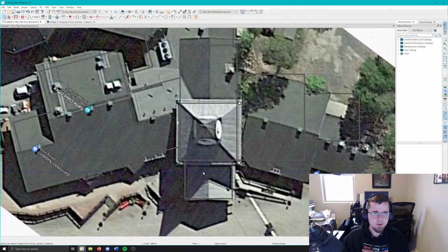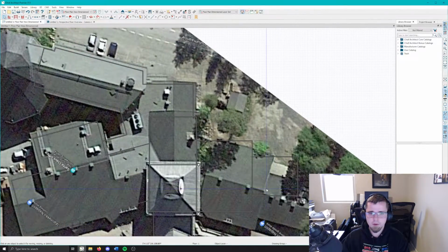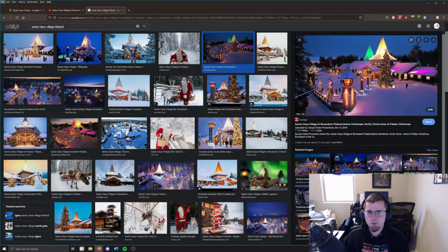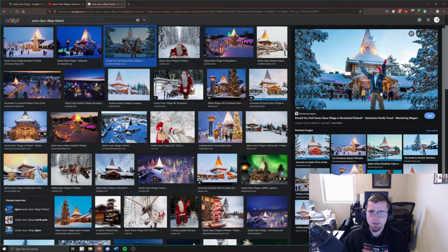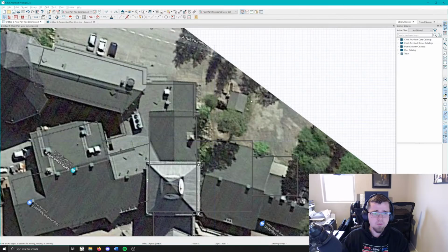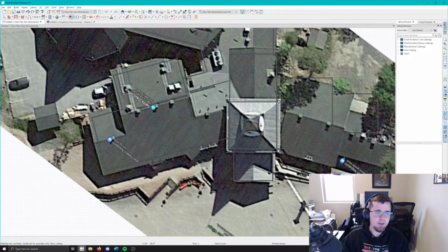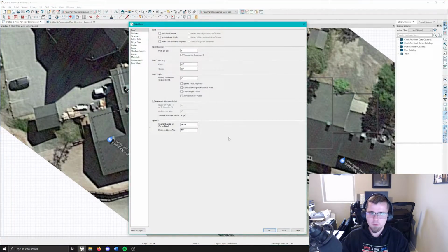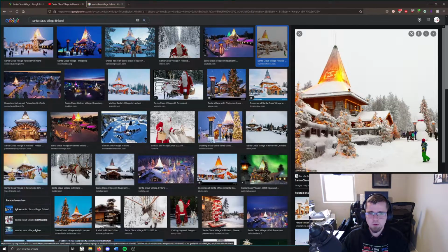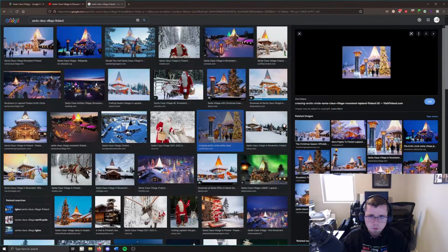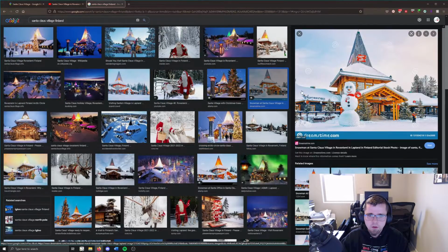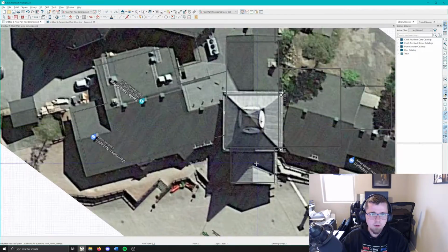Let's go ahead and get some roofs thrown in real fast, why don't we? So now when we're figuring out that roof pitch, this is obviously just eyeballing. We're gonna say that's probably like a 4/12 pitch on the bottom. What I'll do is I'll eyeball it real quick like that, throw them in, and then compare. If it looks close, I'm happy. If it's off, then I'll adjust it. We're gonna give it a 30-inch overhang all the way around, keep the rest the same. And actually, real quick, let's see if we can change the roofing material. See if we need to. We could make it snowy. Let's leave it as is for right now.